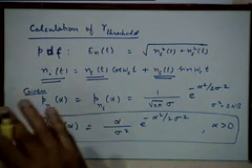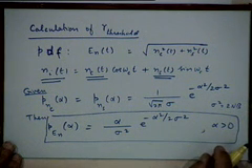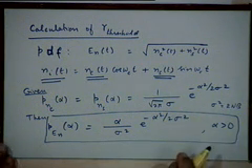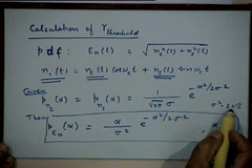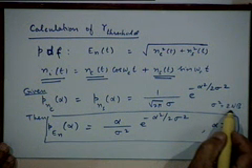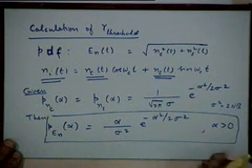What is the bandwidth of that filter? 2B. What is the noise power spectral density height? N0 by 2. So, N0 by 2 into 4B, 2B on the positive frequency side and 2B on the negative frequency side. So, sigma square is the noise variance, which is the power in the noise signal, which is the area under the power spectral density function, which is going to be equal to N0 by 2 into 4B, right. So, sigma square is 2N_0B in our case. Is this calculation understood? Good.